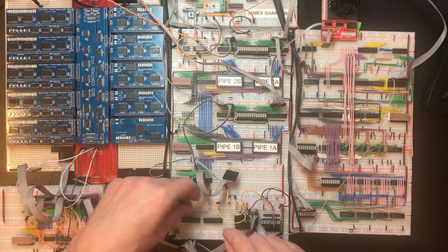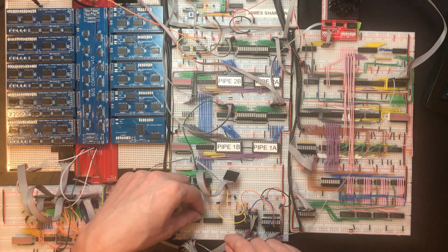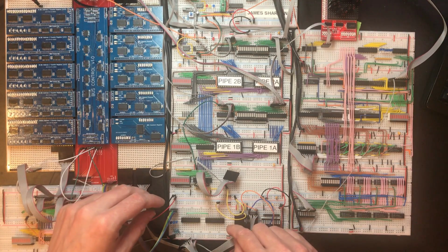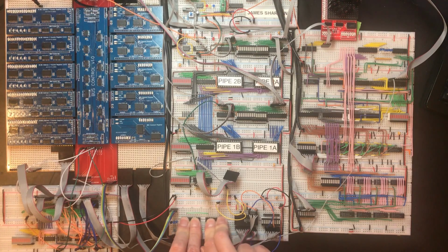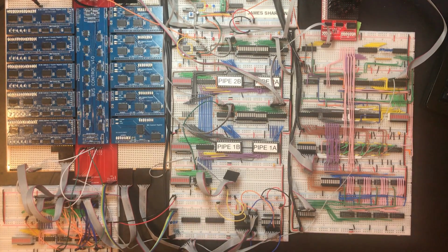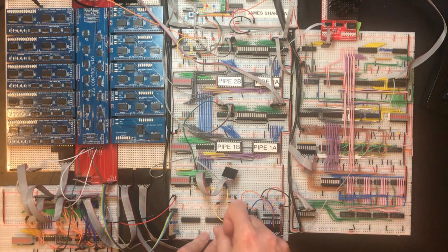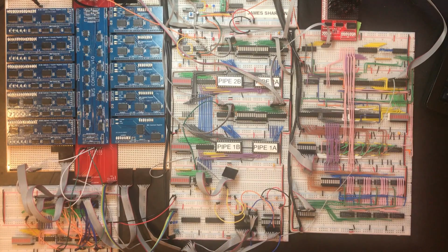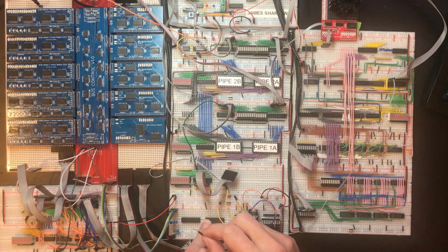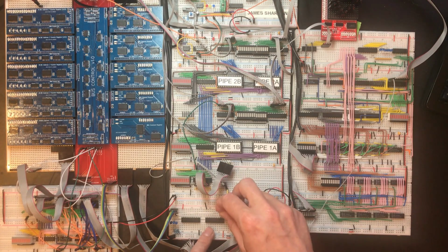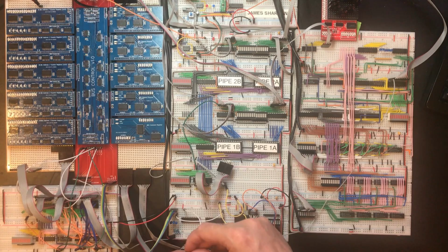I'm going to position these chips to match these green wires I've got. So that should work. Power, ground. Be a bit more careful on this side. Right, so this is going from memory data bus to the main bus, so this needs to come from assert. And this is the one that comes from direction.